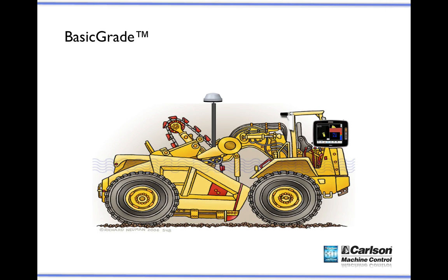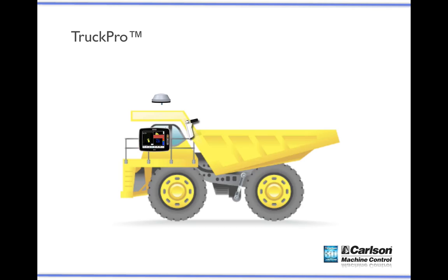I think for bulk earth moving and rough grading, this provides one of the simplest systems for scrapers. If I use my control box, enable the internal receiver, I run one cable to power, one cable to the antenna, and I can either stream the RTK correction via the SIM card slot or add the RTK radio. And I have a 3-year warranty on all of this. It's very powerful, simple, easy to install. If there's an issue with the system, fewer components with more integration make it very simple to troubleshoot.